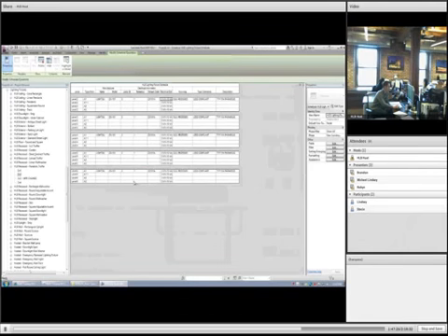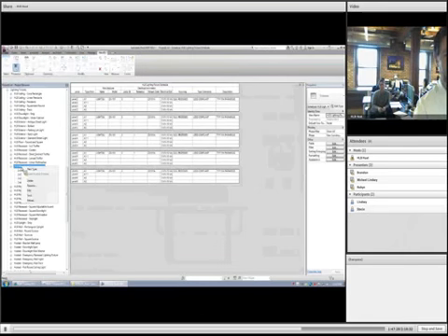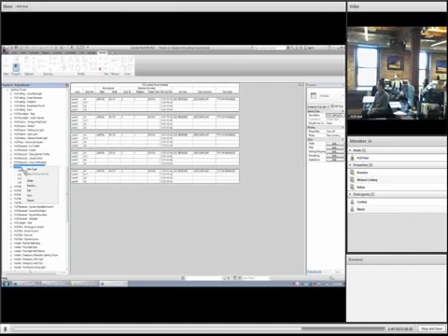It's maybe not a bad way to go, and that's fairly easy to do. We would just hit duplicate at the beginning, name it what you want. From day one, we don't touch the fixtures. We always start with duplicating. Right. Then as I go to level 3, and I know we did a markup, I need to place an F1. I can then find it in there. I don't need to try and remember that F1 was a 6-inch compact fluorescent wall washer. I can find a name that says F1. Correct. I think that's a great way to go.